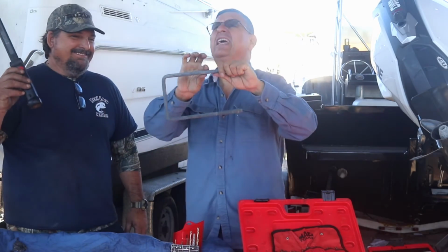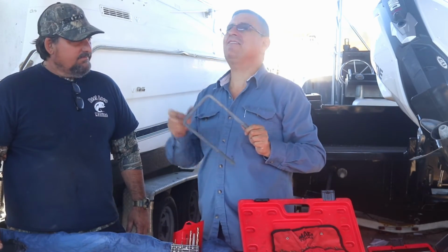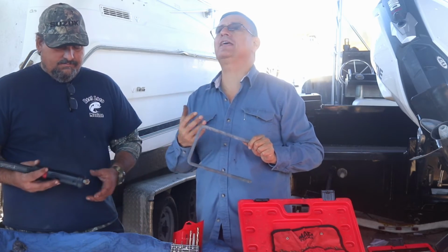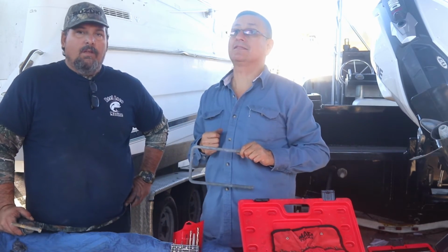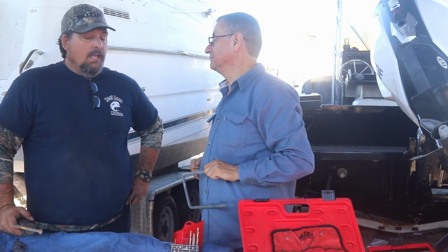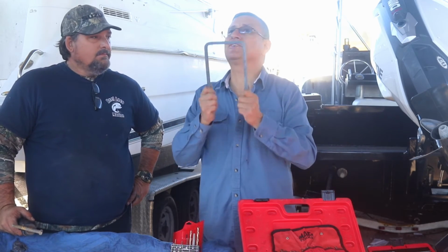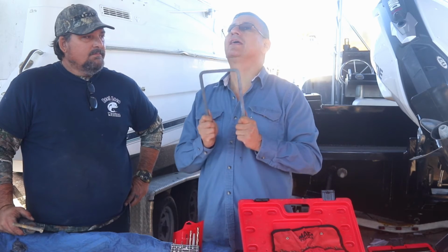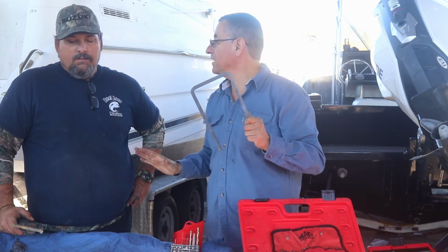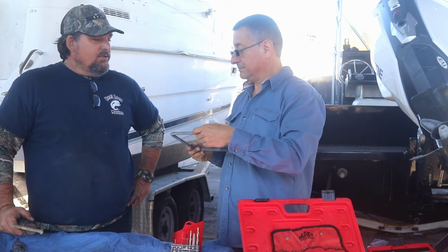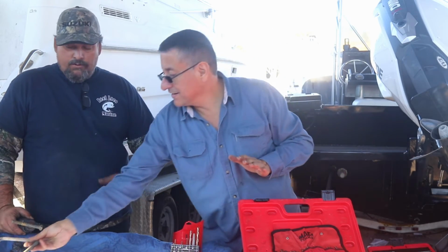It's hard. This is galvanized. Galvanized in marine application is the enemy because it's covered with zinc, and the zinc attracts the oxygen. Absolutely. In marine application, this is not good. This is the enemy. No galvanized pieces of anything in marine applications. The only galvanized you should have is on your trailer. On the trailer, that's it, because it has more integrity.